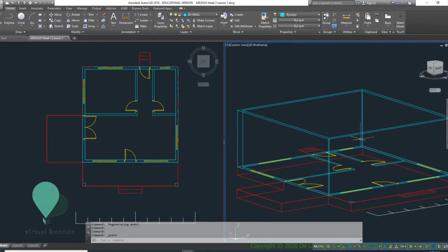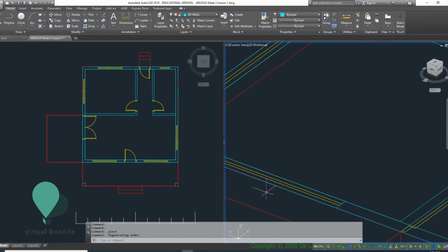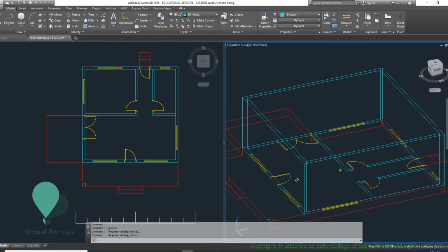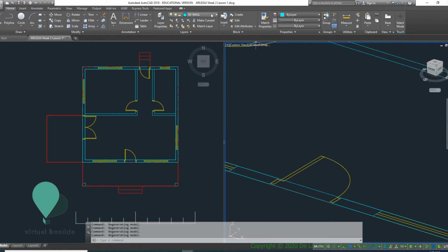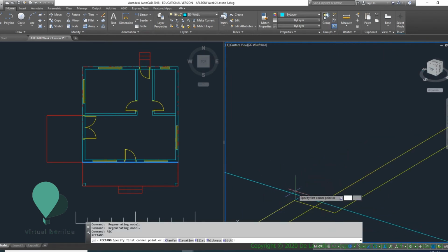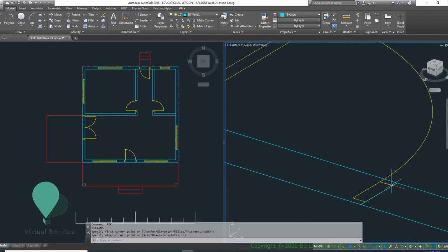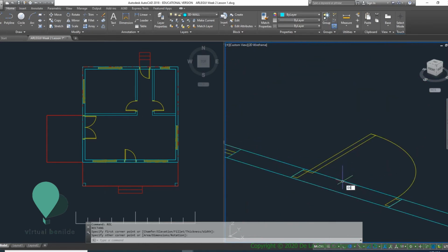So now we're going to proceed into making holes for the windows. And the way to do windows is to punch holes into these. So again, we're going to invoke the command. Let's start with the doors. So I'm still in my layer 3D wall. I'm going to create first a rectangle from this corner, of course the hole, avoiding the door jambs. Extrude this first. Okay, that rectangle.